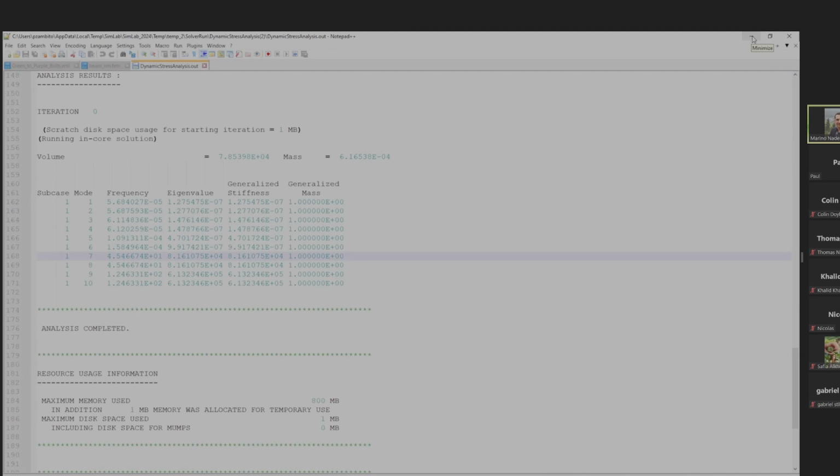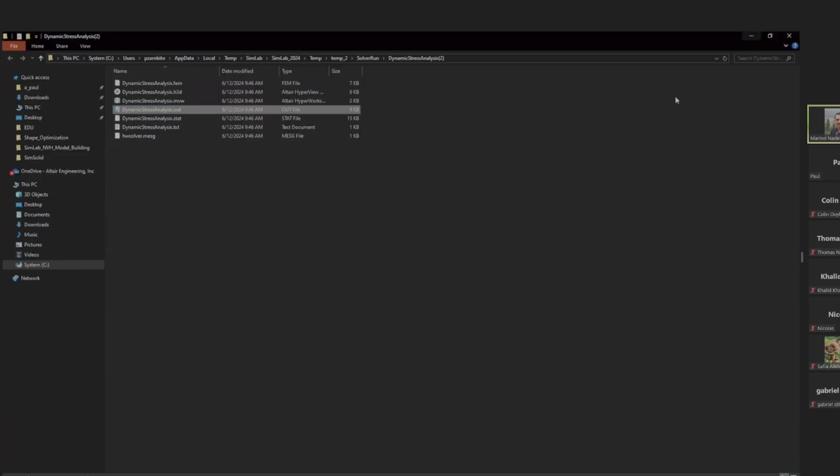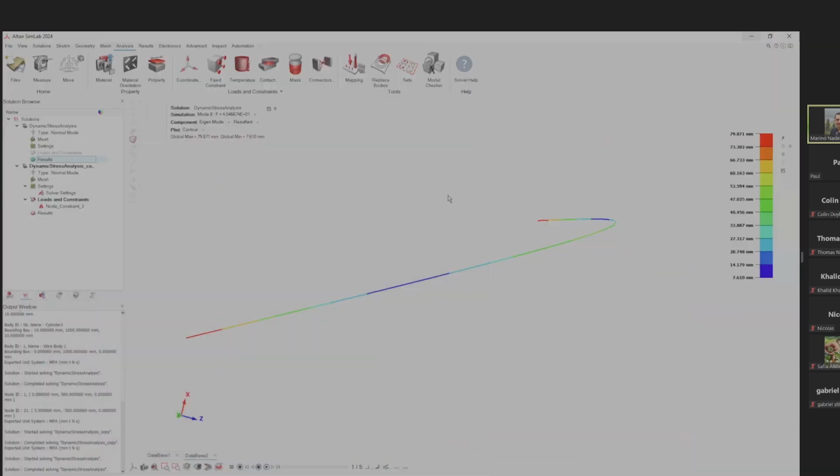Zero is not a real frequency. So it's like 5.68, the first one. It's all negative 0.5. Is there a way you can suppress these, tell the system you don't want to see them, or will that have to go to the bulk data input? We don't want to go there. I'm just asking, is it more sophisticated? It's been a while since I've done these.